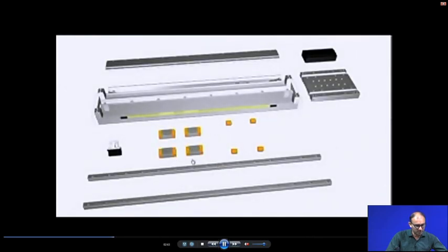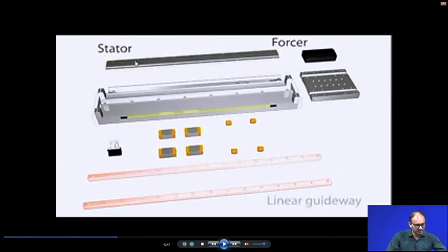Right. So, these are the different components of the linear motor. This is called the forcer. The forcer is the part which will be put onto the top surface, and the coil will be wound around this forcer, and this is the plate which will be on top of the forcer, and you put any component here. Suppose you want to move a workpiece, then put the workpiece here. If you want to move a tool, then mount the tool here, like that. And this is the stator, because we know that stators are required so that you can put the magnets here, and because of that magnet you can get the motion of this forcer on top of the stator.